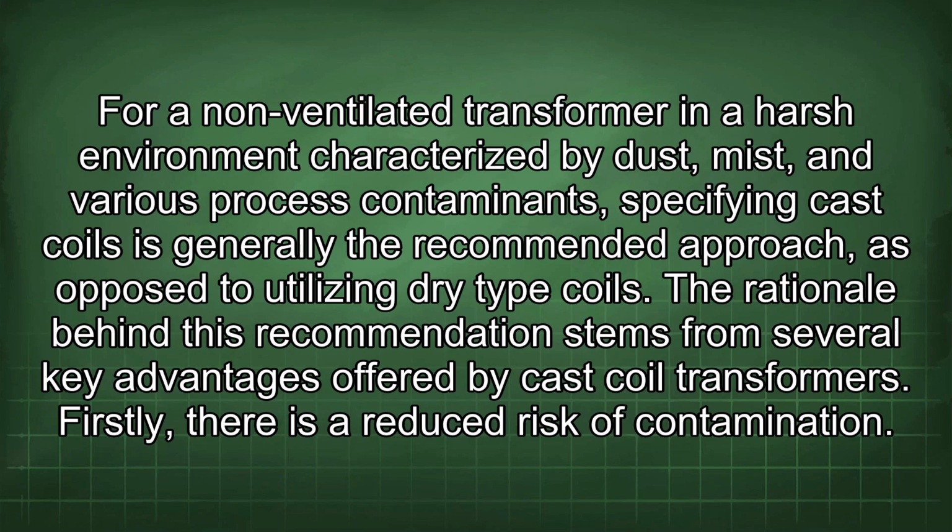For a non-ventilated transformer in a harsh environment characterized by dust, mist, and various process contaminants, specifying cast coils is generally the recommended approach, as opposed to utilizing dry-type coils. The rationale behind this recommendation stems from several key advantages offered by cast coil transformers.